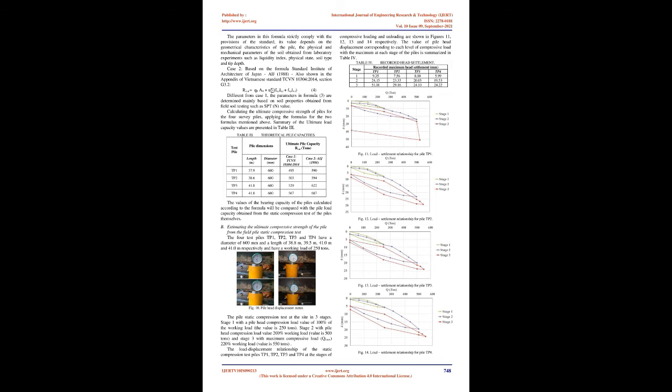These points are connected until a straight line is formed. The cross of the straight line with the loading axis is the ultimate load. This method assumes that the loading curve forms the shape of a parabola. Therefore, the value of the collapsing loads obtained by using the Mazurkiewicz method should approach 80% of the standardized criteria.